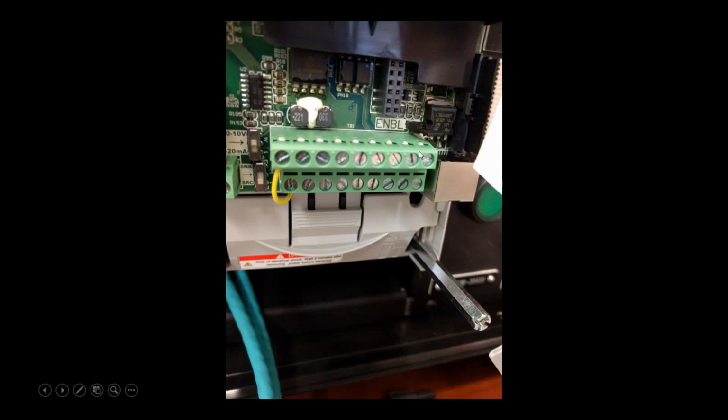If I crack open the inside, this is what the HMI looks like on the inside when I take the cover off. There's two extension screw sets, and a novice programmer may think, well, this right here looks like an Ethernet port. I can just plug in. No, that is not set up to communicate via EtherNet/IP. I think, if my memory serves me correctly, it is DSI communication or Modbus, but I don't remember 100%. But these are the terminals to do direct. So if you don't have an Ethernet adapter and you want to communicate with an HMI, these are the terminals you'll be using right here.